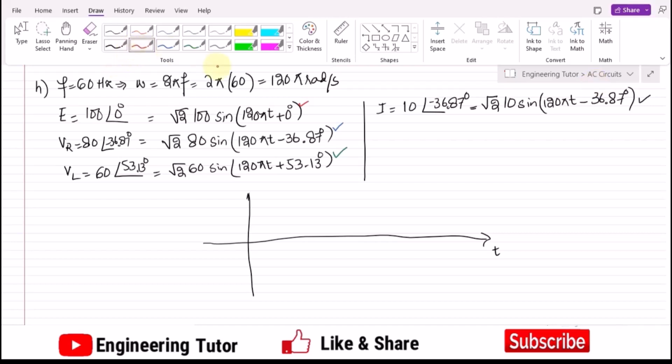voltage here. So for plotting the voltage, the phase angle is 0 degrees. So it is now very easy for me to plot them. Okay, so that is the value of the voltage. So the peak value it has is this square root of 2 and 100, and this is the negative peak value, which is minus square root of 2 and 100. Okay, so now after it we have V of R, the angle it has is minus 36.87, so that's why this is the representation with this one.